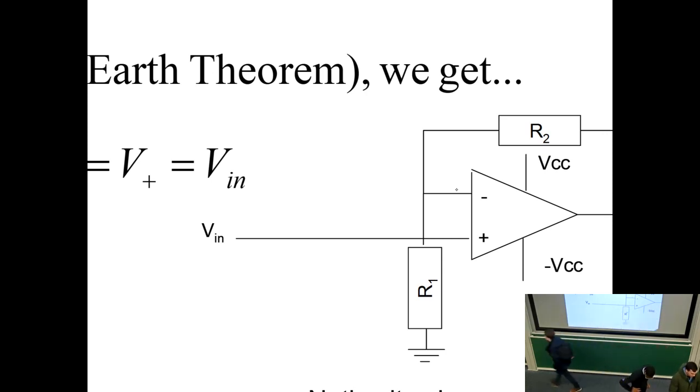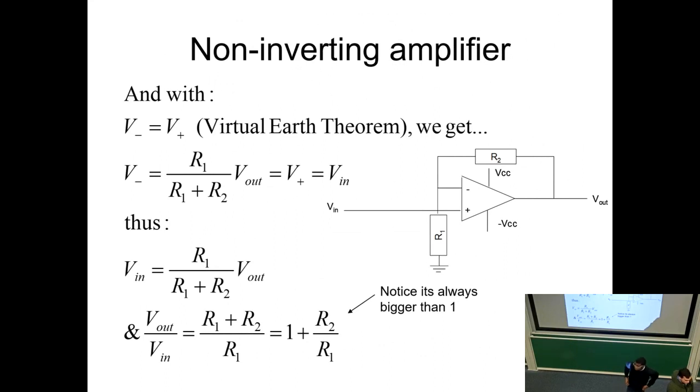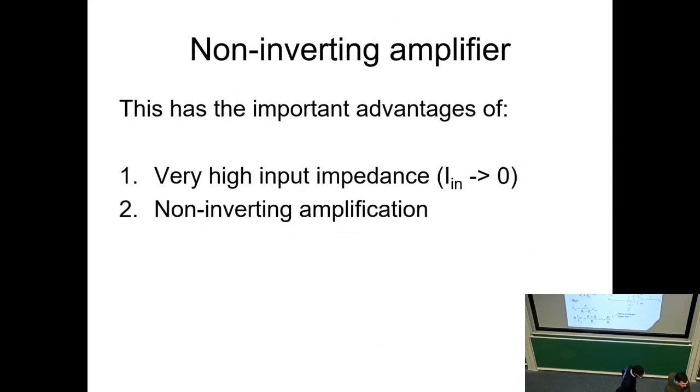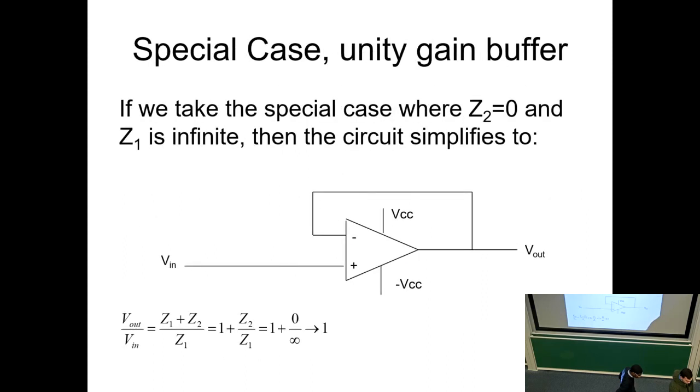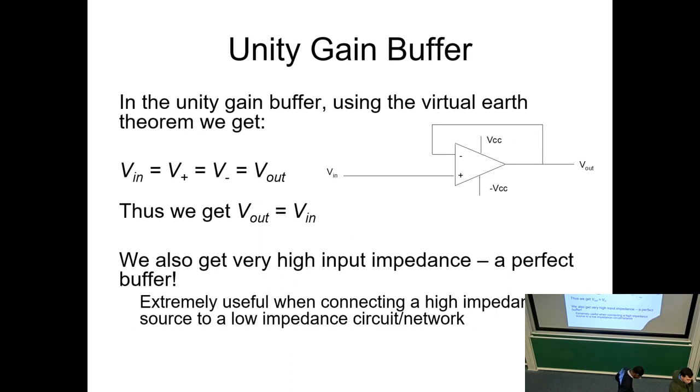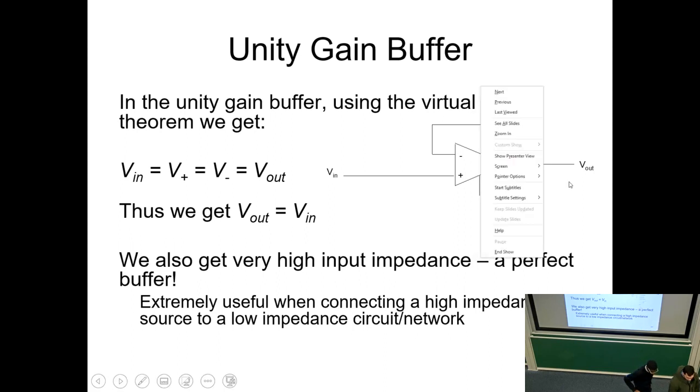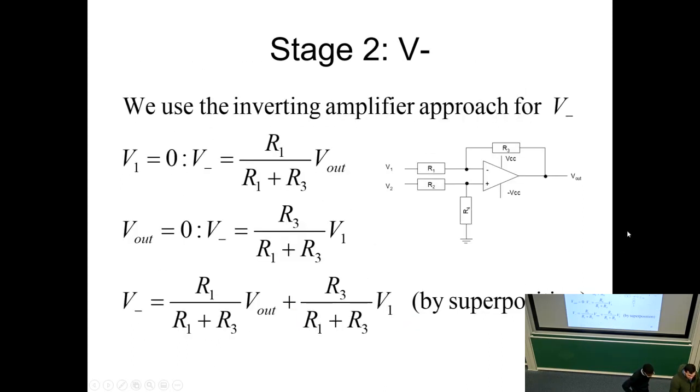Okay, so just to confirm, I know you said it, but the simple concept is the virtual earth theorem, it's just the assumption. Later in the subtractor, we can use that simple concept of KCL: since we know that one of them is attached to ground, let's say the non-inverting, then the inverting is not, and at that point both of them are zero. Then we assume that whatever current is coming here and whatever is coming here, because of KCL, results in this being 0 and this 0. Yeah. And we can just, like you said, simply use this 0, and then use that to work out what's going on here.